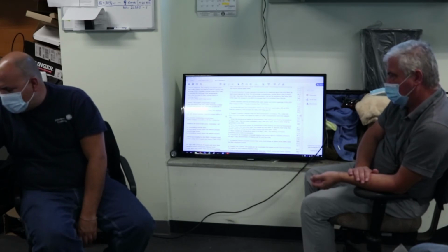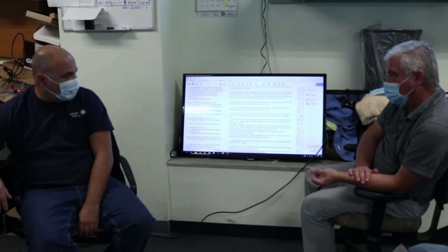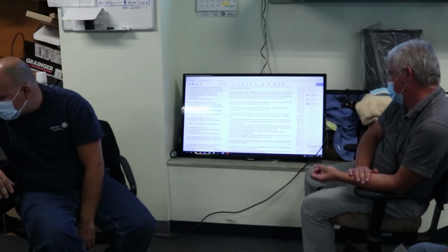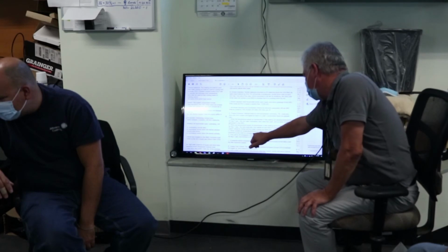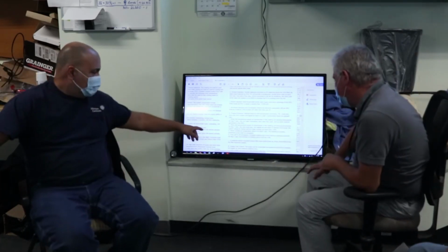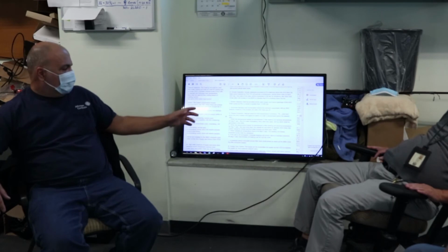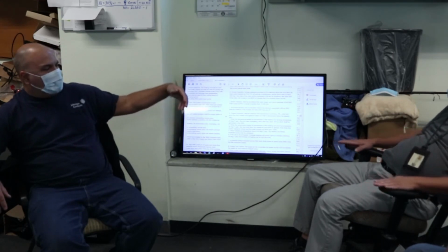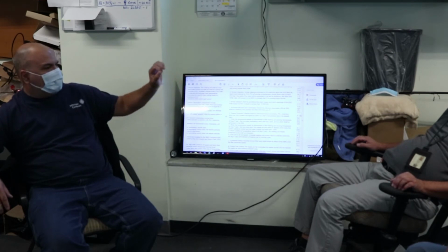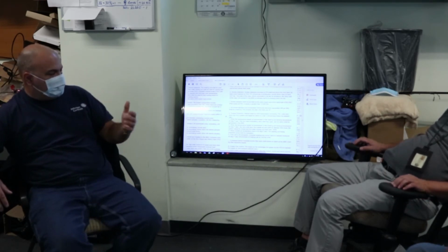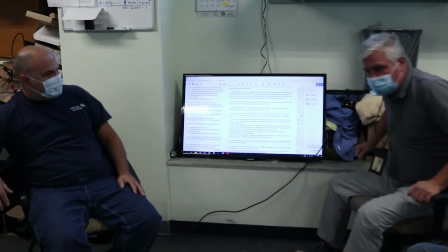So it will come on. The pump will come on if the outside air temperature drops below 40 degrees. Okay, I see. So anytime the outside air temperature drops below 40 degrees, it's going to come on. But you're going to maintain a low limit protection of 45 degrees in that chamber. So it's going to look to maintain 45 degrees in that chamber, and then it's just going to put that freeze pump on just as added protection.